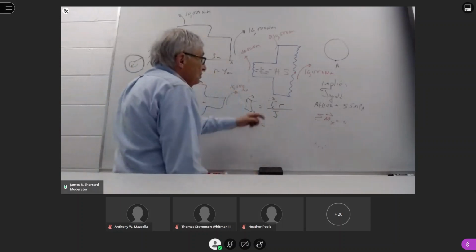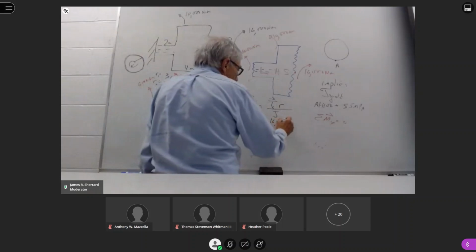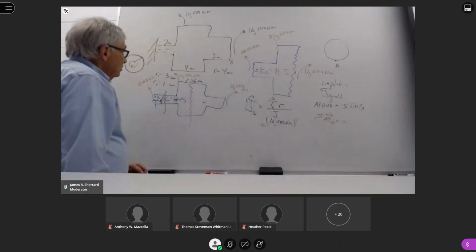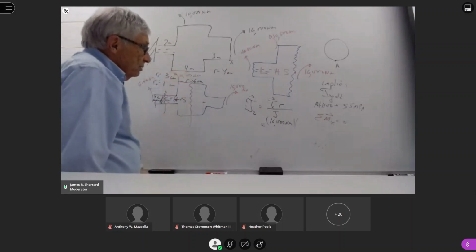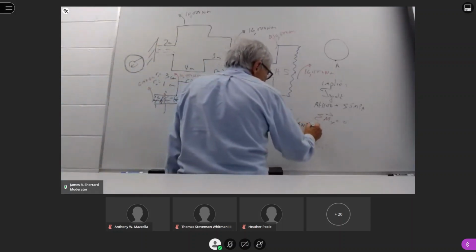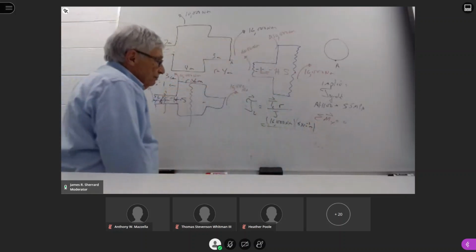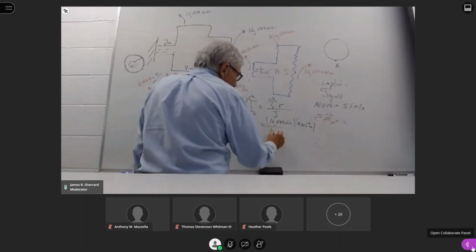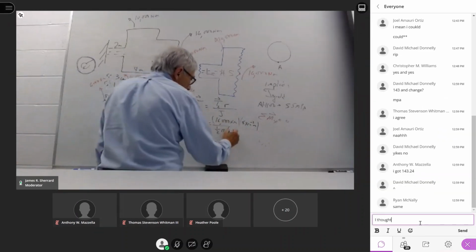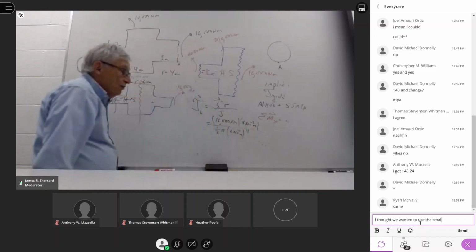We've just found out that that torque is in fact 16,000 Newton meters. The radius for that section was 6 centimeters. And the J, since this is solid, that physical property turns out to be 1/2 pi times R raised to the 4th.